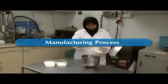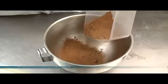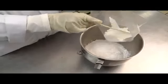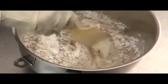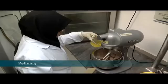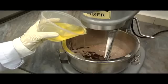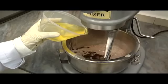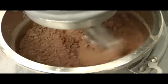Manufacturing process. Raw materials, for example, cocoa liquor, sugar, and milk powder, are mixed with an adjusted fat content at roughly 26% before the mass is refined. Chocolate paste is refined usually with a roll refiner to obtain the required smoothness. The mass is ground until 80% of particle size distribution is between 20 to 30 microns.